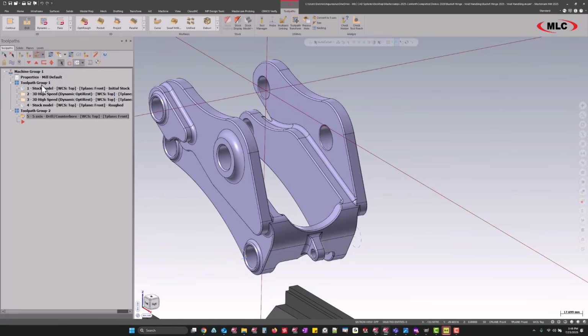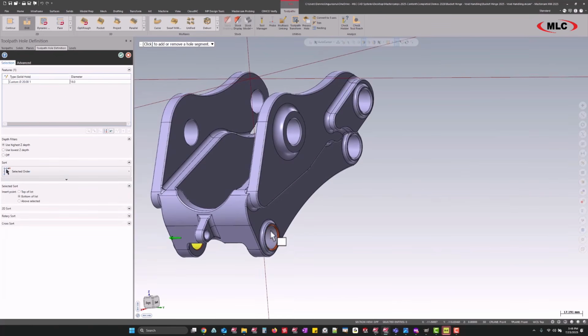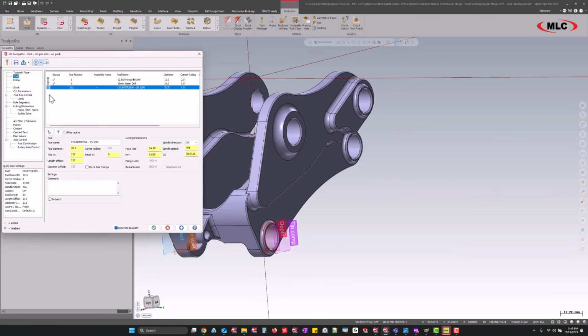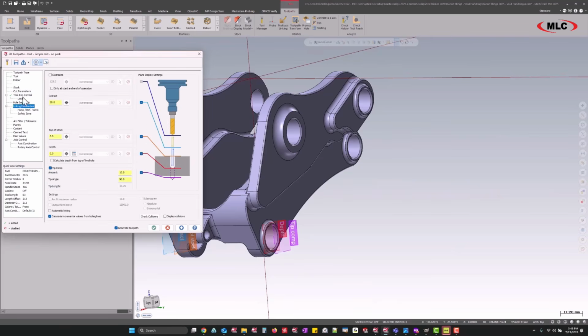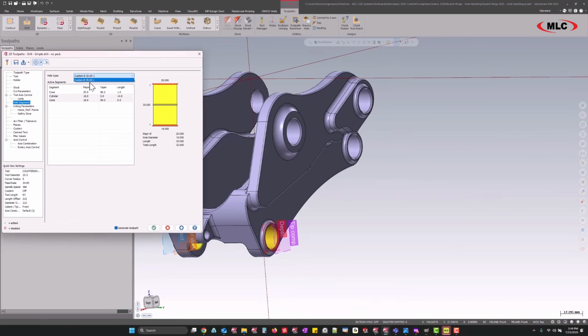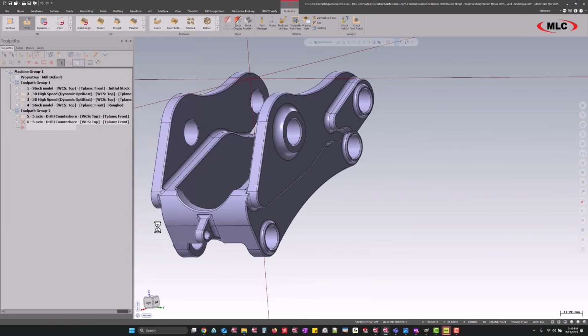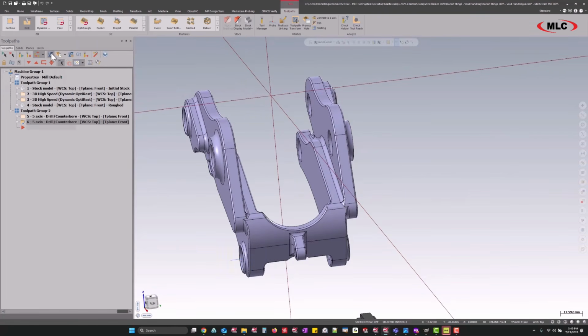But the problem is afterwards, when I go back and want to countersink, if I select both of these surfaces, well, that's kind of where there was a little bit of a limitation here. And if we throw this back into 5-axis, notice our hole segments only sees one hole. And if we go back to, let's say, linking parameters and put in our right parameters here for our countersink, well, it's only going to countersink from one side.